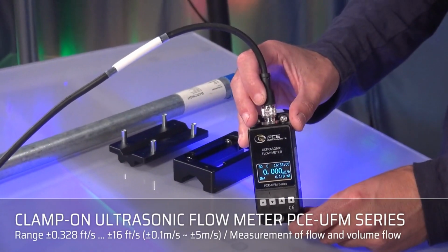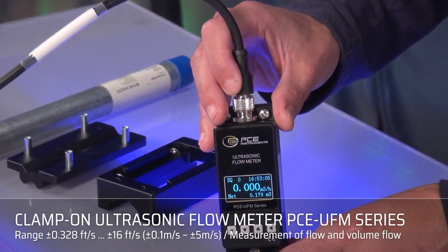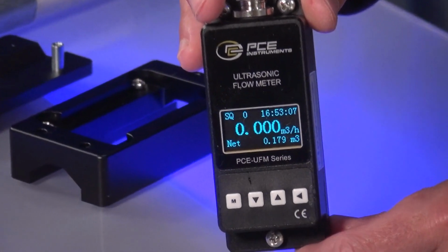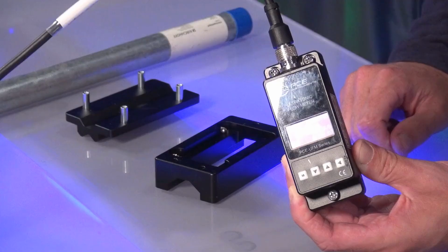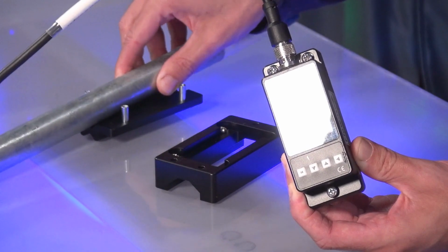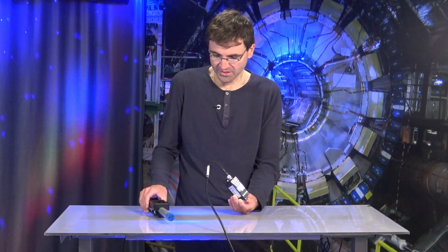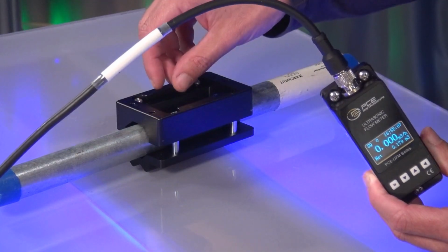Here we see a flow meter from the PCE-UFM series. The UFM series consists of a total of 6 measuring devices from UFM 4 to UFM 25. In this case, we are using the UFM 15. What does that mean? We need to be able to carry out measurements on different pipe thicknesses. And that is why these measuring instruments are supplied with brackets that are suitable for enclosing different pipes from DN4 to DN25, as I show here.